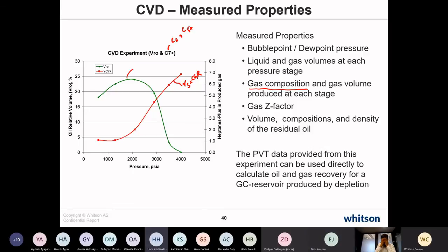And also regarding the gas composition, as I mentioned, if you have very lean gas condensate, then it will be more difficult to accurately measure the composition of the equilibrium gas phase. If you lose a very small amount of the liquid phase in the pipeline from which the gas is flowing when you flash it at surface, or in the single stage flash in the PVT lab, there will be a lot more error in the surface CGR. So, for example, Core Lab generally uses cryo for accurate measurement.